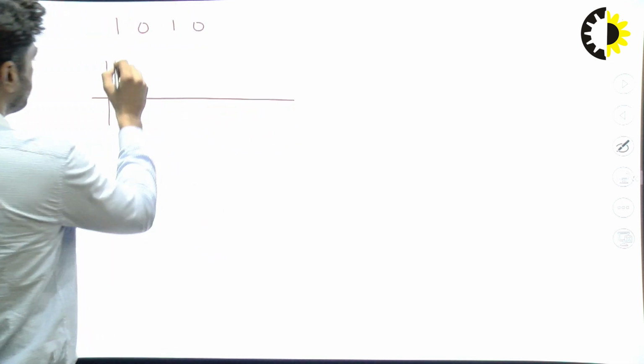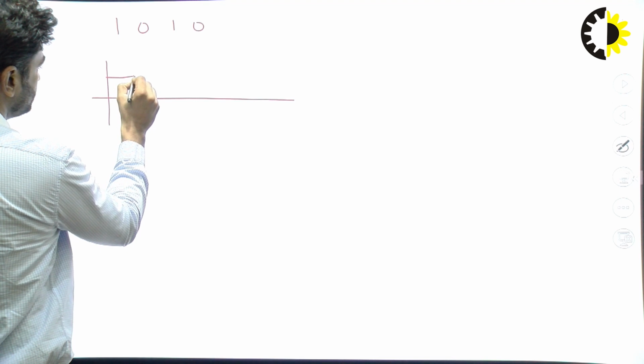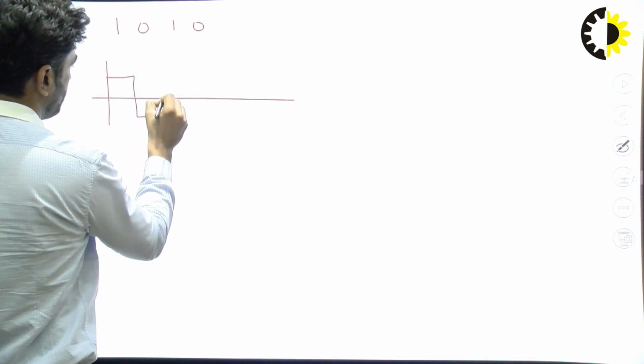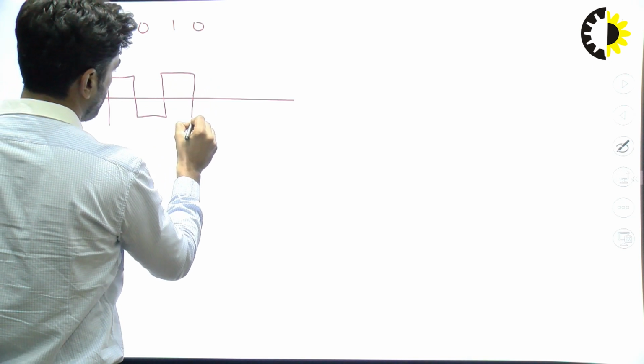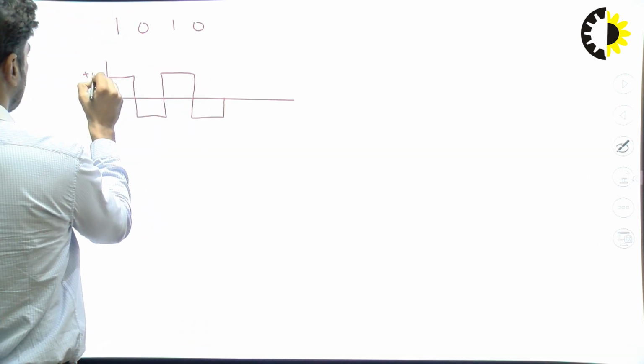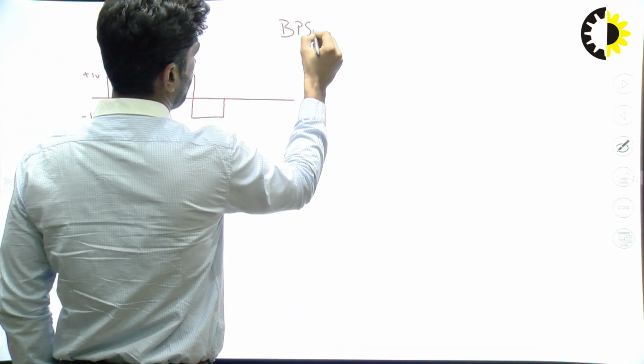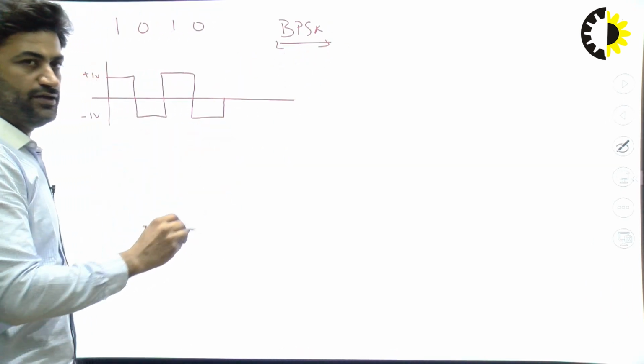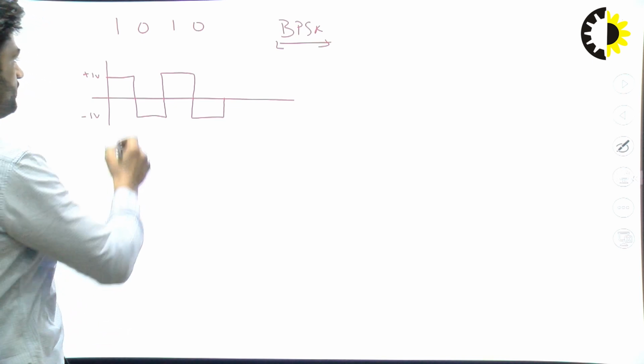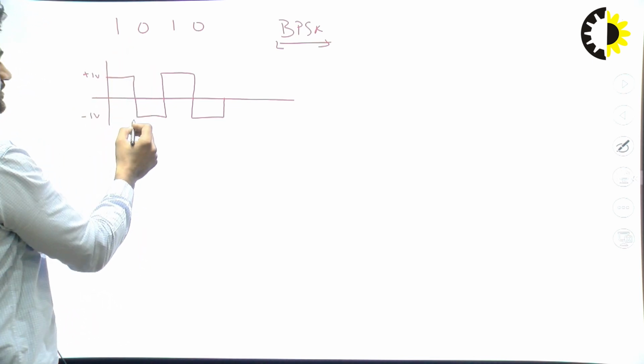Now see here the picture diagram of PSK. Suppose our data is 1 0 1 0. First of all, we have to do the line coding for this signal. So we will use polar NRZ. 1 will be represented as +1 and 0 will be represented as -1, that is +1 volt, -1 volt. Now BPSK, binary phase shift key, has our binary data as the modulating digital signal. 1 will be represented as a plus voltage, 0 will be represented as a minus voltage.